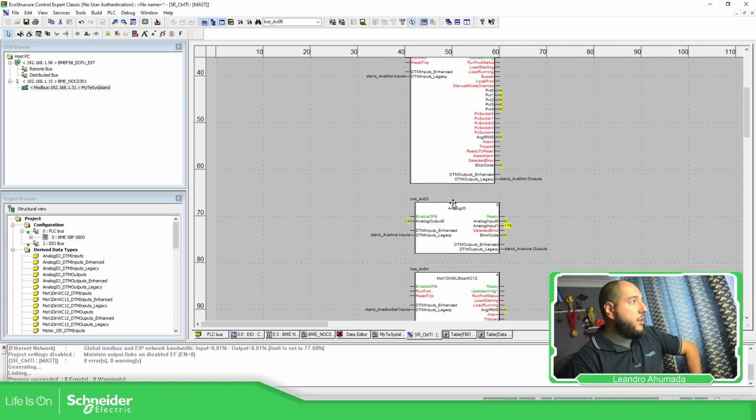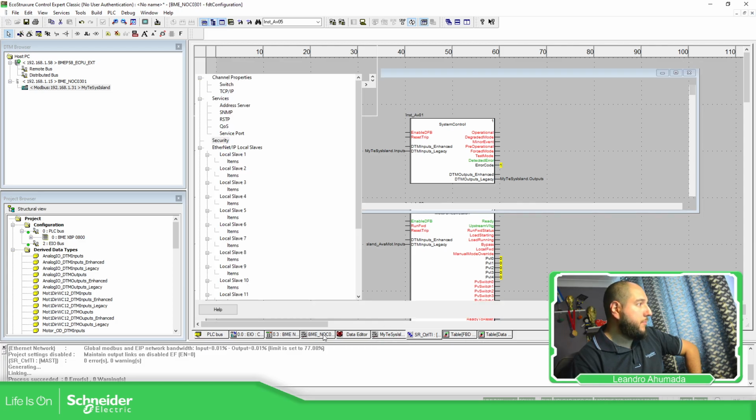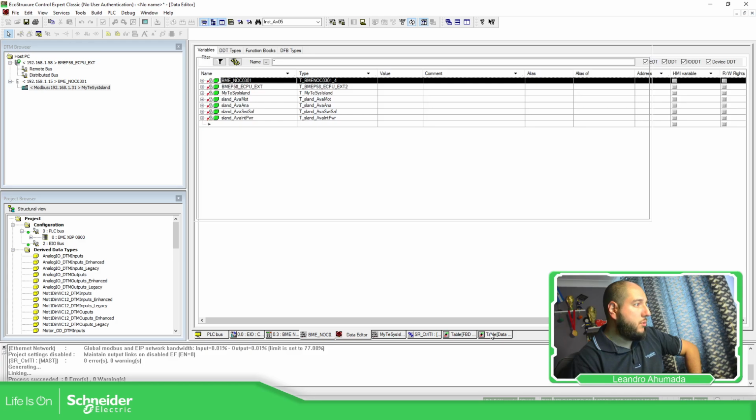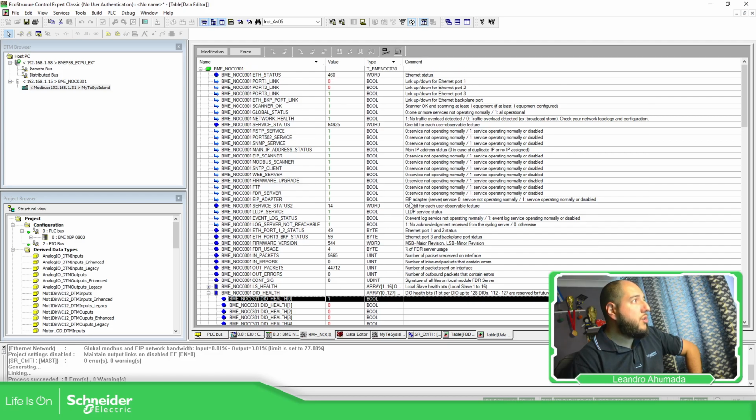Okay. Then in addition to this, it's important that before executing something over here, we check the information related to that particular device. Okay. In the newer version of the firmware of the TeSys Island, we have the possibility to define the behavior in degraded mode, that is, when you don't have communication with the PLC. How do you want to treat each individual avatar when you lose the communication with the PLC? So we have that in the newer version.